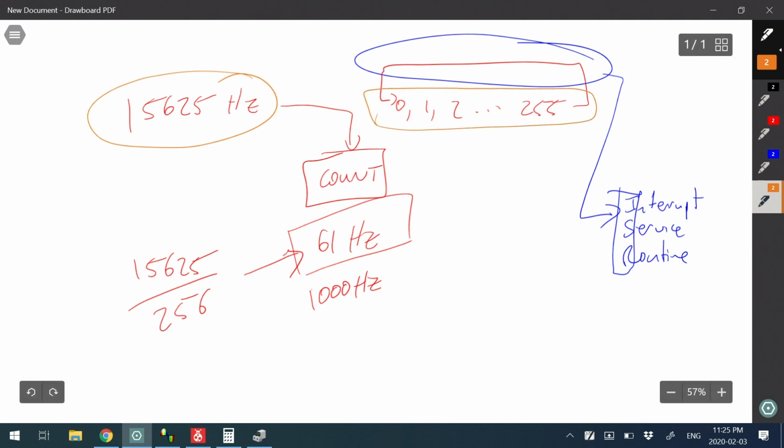These are the only two things we could adjust, 1 and 2. The first is adjusted by the prescaler, CS00, CS01, CS02, which is in the datasheet. The second we adjust by changing our reload value.